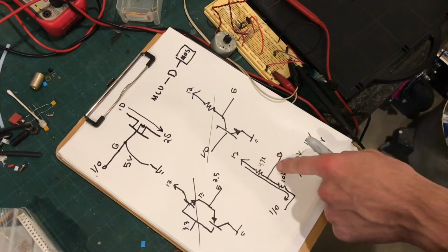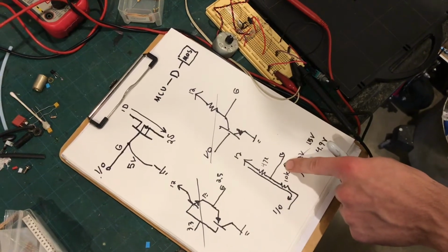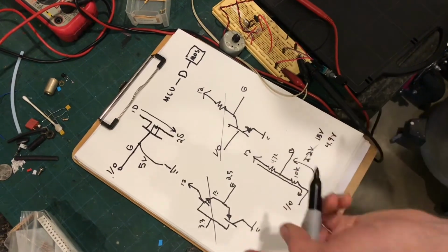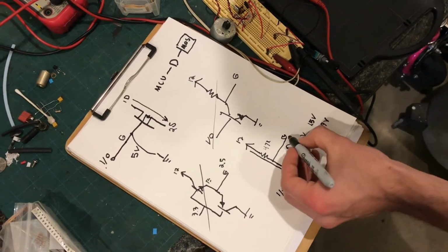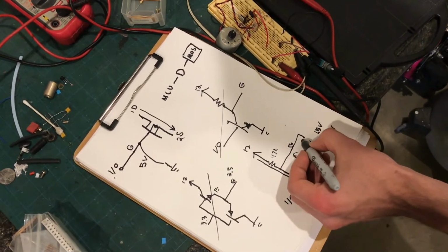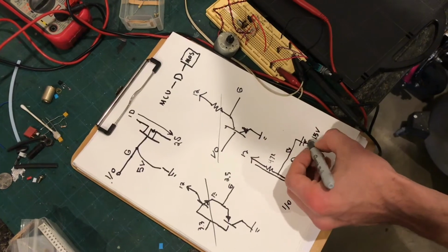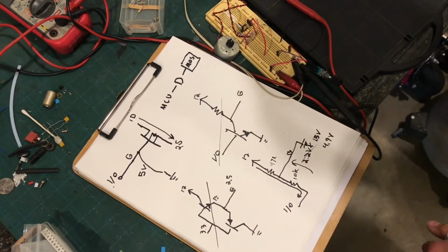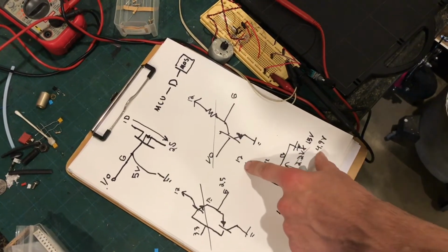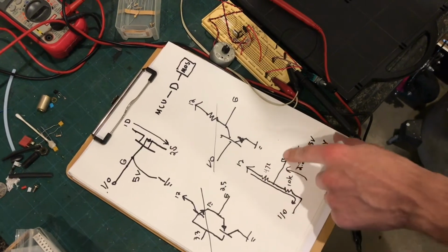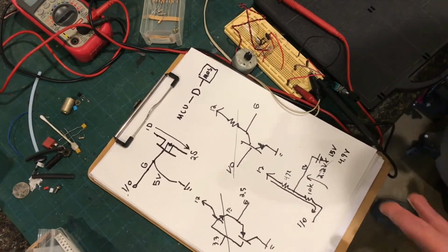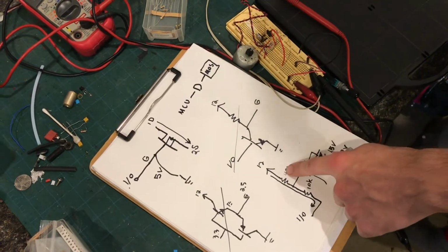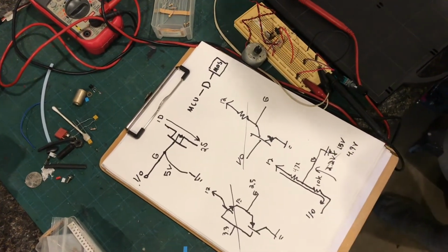So this really only works with low frequency switching because, well, the thing about MOSFETs is they don't change their speed instantly. They actually act like a capacitor that has to build up charge in order to turn on. And if your current's flowing very slowly through a high value resistor, it'll take a long time to turn a MOSFET on and off. But we can't drop these values too low, otherwise we could damage the I/O.